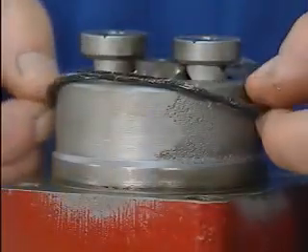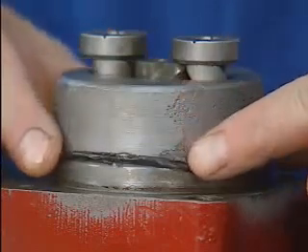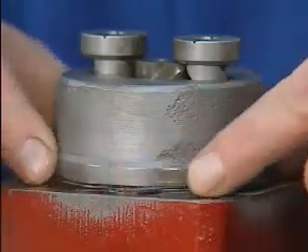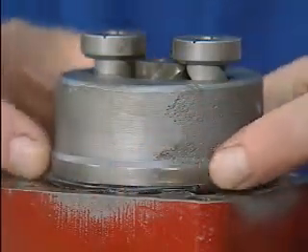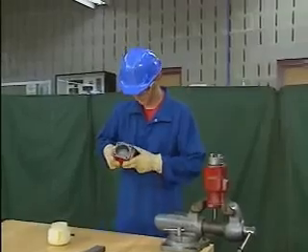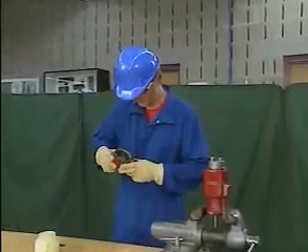Next, the mechanic places the O-ring onto the sleeve on the flange. The lubricated O-ring should fit easily but snugly into position, with just enough room to allow for compression. Once the O-ring is in place, the next step is to assemble the flanges.